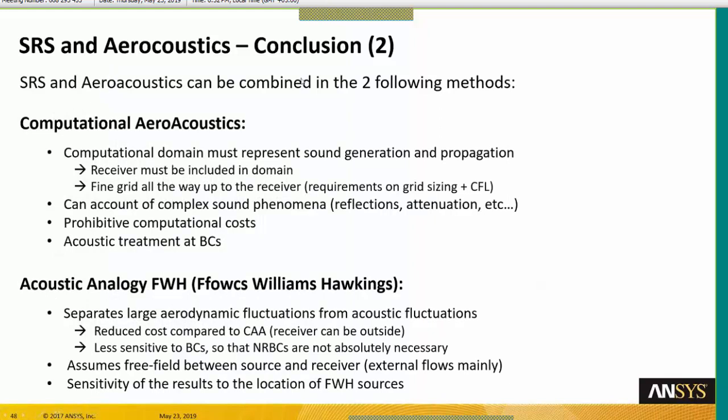SRS and aeroacoustics can be combined in the two following methods. The direct computation of aeroacoustics. Remember the costs, the requirements in terms of temporal and spatial discretization. You can account for complex sound phenomena, but it's usually prohibitive in terms of computation cost. That's why you usually have very small domains. And remember that you need some special acoustic treatments at the boundary conditions, at the borders of your domain.